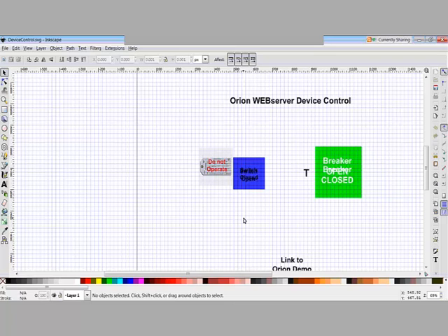And the term tag refers to an informational or control tag that either lets the operator know about a condition that should be known before control is attempted, or blocks control, either blocks the closing of a device or blocks both the opening and closing of a device. These are the different kinds of tags. And again, we'll go into that in a second, but let's focus on control at this point.